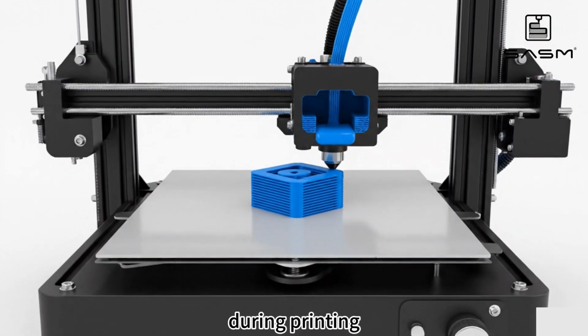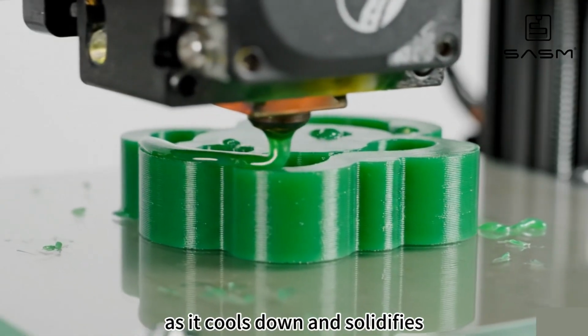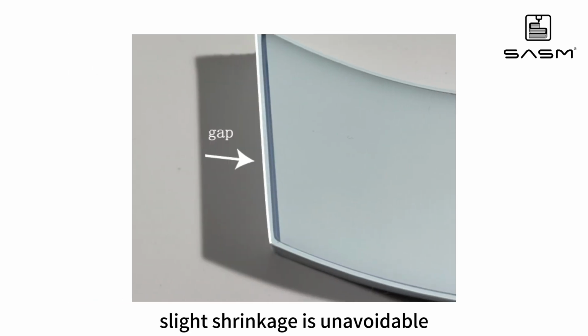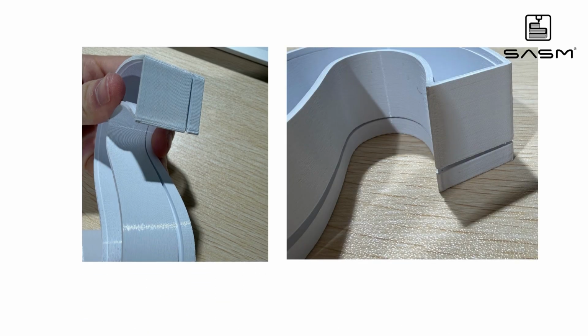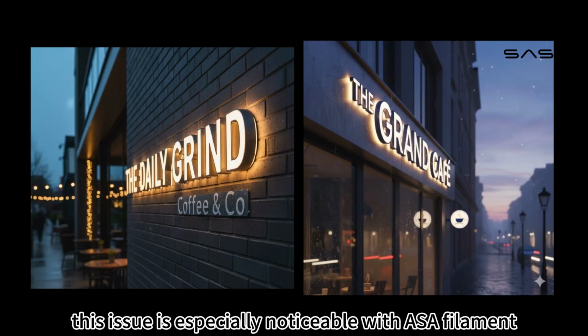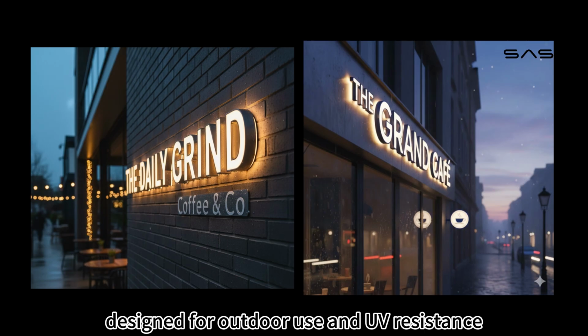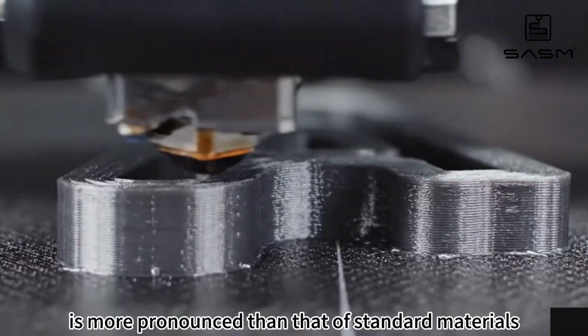During printing, the filament is in a molten, liquid state. As it cools down and solidifies, slight shrinkage is unavoidable. This easily leads to problems such as the letter shell and the acrylic not fitting properly, or male and female parts failing to align during assembly. This issue is especially noticeable with ASA filament designed for outdoor use and UV resistance, as its shrinkage is more pronounced than that of standard materials.